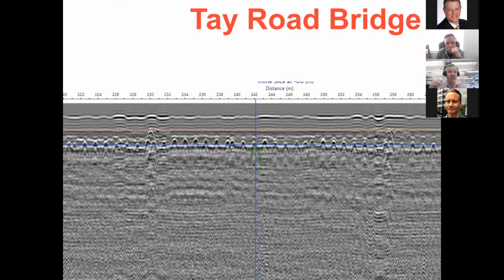Basically, you imagine this, right? I'm going to try and do this with my hand. Here it's scanning, and it's 3-dimensional scans. What it does is pick up the rebar. This is the rebar. It thinks the rebar is closer directly below, so it's further away. As I move the antenna closer and closer directly above, the hyperbola comes up and hits this peak. Here we are now, closest point. Now I move the antenna further away, and the mathematical shape changes. You're getting further and further away from this rebar, but it looks like it's further away, and you get this mathematical shape. Sorry if that's an awful explanation, but that's what's going on.